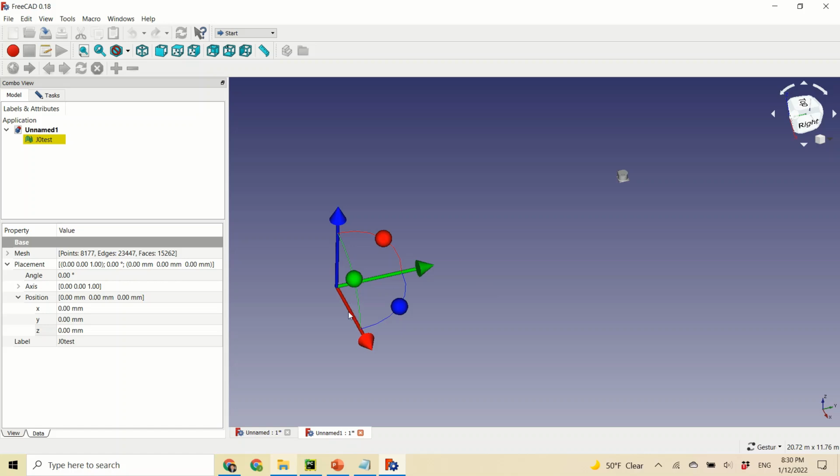The red color indicates the X direction, green indicates the Y direction, and blue indicates the Z direction. First let's move in the Y direction, we need to move in the Y minus direction. I roughly know the number, so minus 11,000. So it's moved to here, and in X, you need to move in the X plus direction, which is 2240. Okay, and let's look at it from the top.